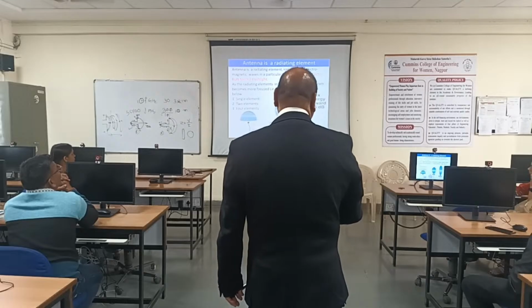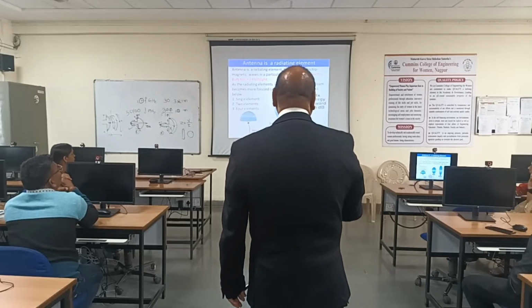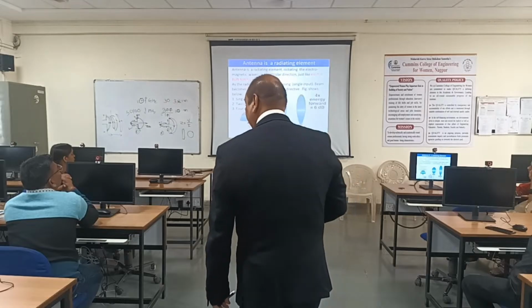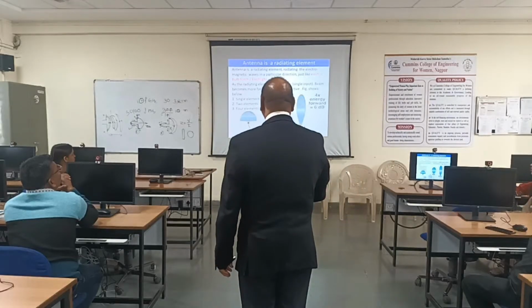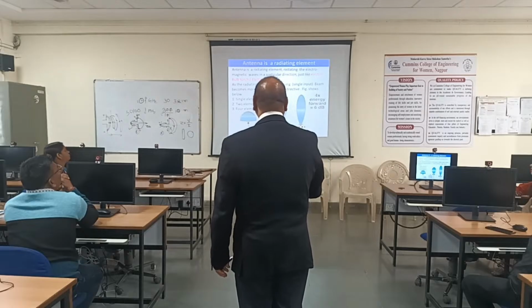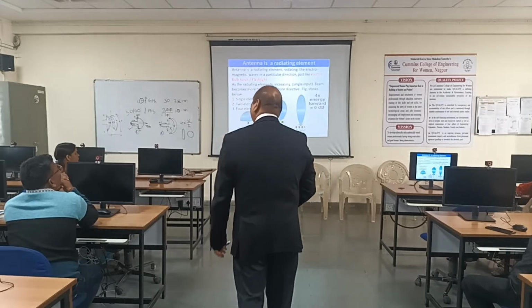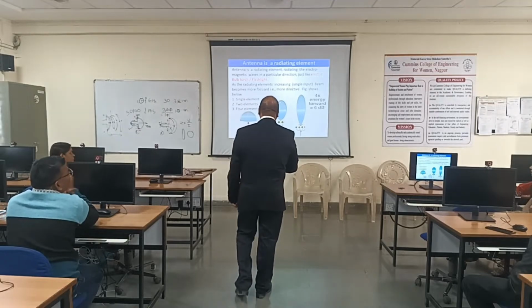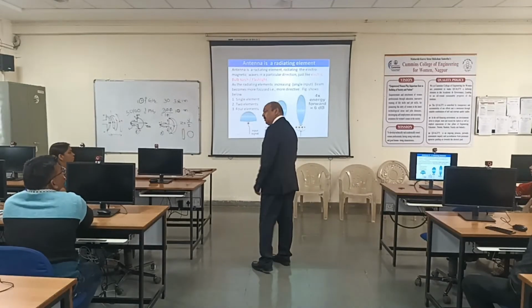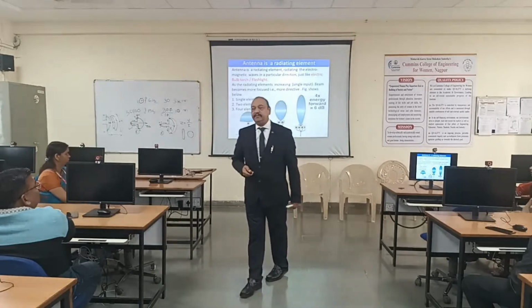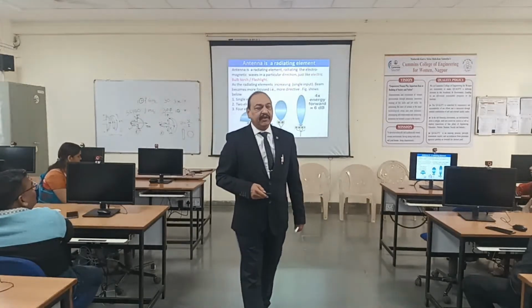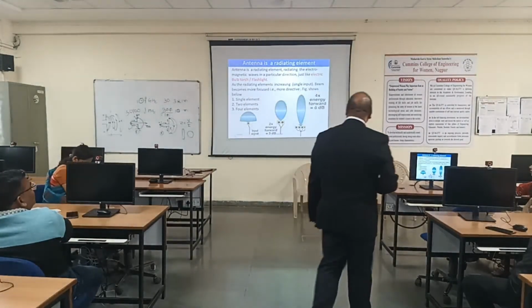And if you go for 4 elements, the total power is increased by 4x. Here 1x, 2 elements 2x, 4 elements 4x energy in the forward direction, gain increased by 6 dB, 3 dB here plus an additional 3 dB here. Total becomes 6 dB. So 4 times energy is increased. Next.